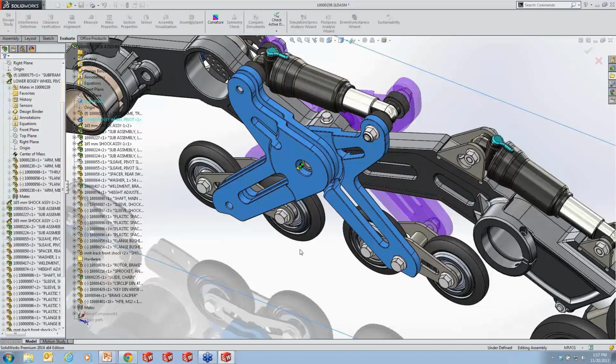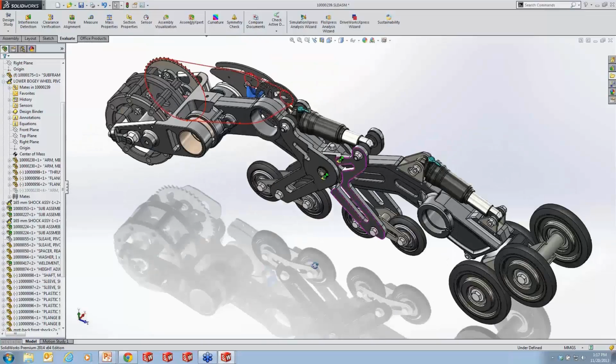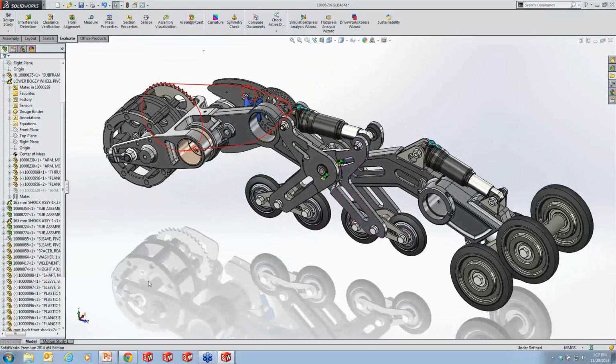So I'll go ahead and just suppress this guy again, bring everything back to order. But you can use that bounding box. Oh, by the way, there's this part still hidden. Just remember, you can tab to hide a component and shift-tab to show it again.